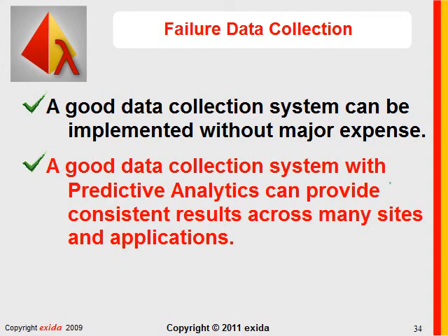The predictive analytics technique is an excellent way to build confidence in your data, and it's the kind of confidence that I think you need before you start doing things like extending proof test intervals. I mean, what if your data collection process was like one of the examples I gave? Simply not getting all the failures.